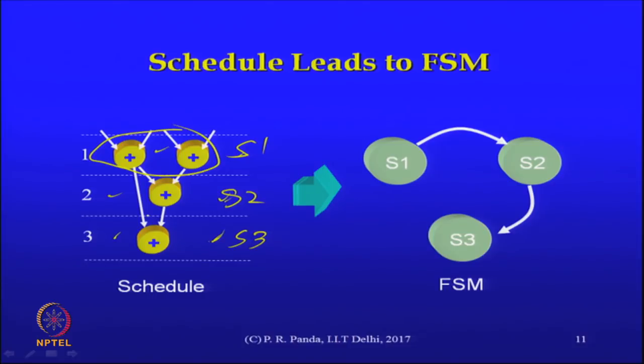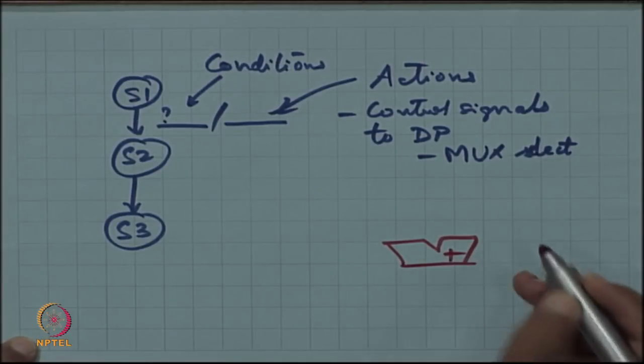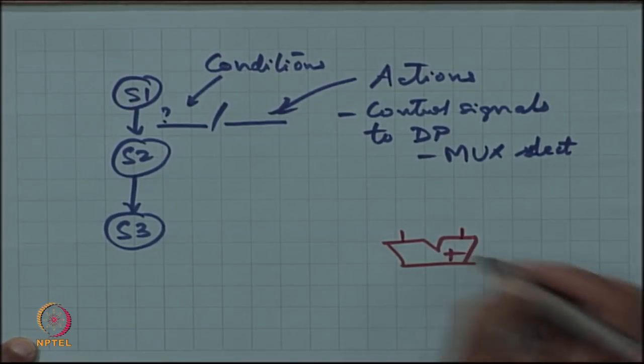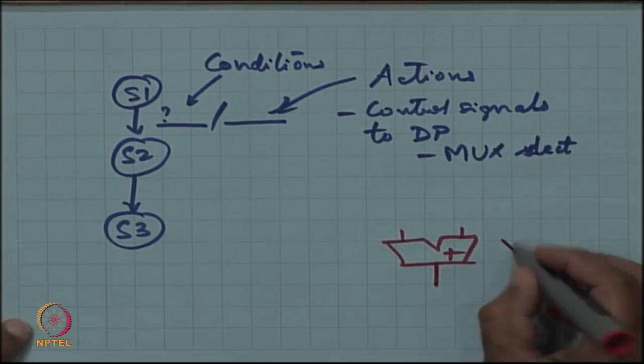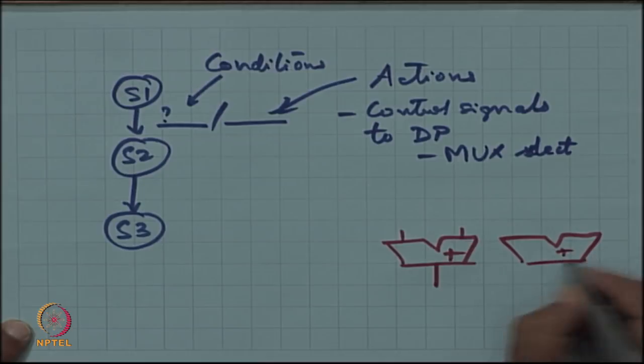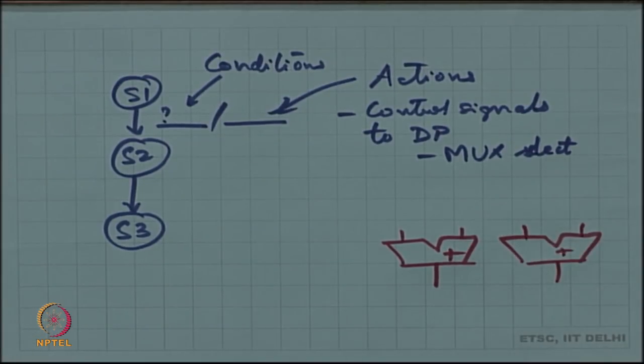What else would be there in addition to the adders? Registers. I have two adders, but the inputs come from somewhere and go somewhere. The important thing is that an adder may be shared across multiple clock cycles. So, actually inputs to one adder may come from multiple sources. That implies what else is there in the circuit other than the adder itself.